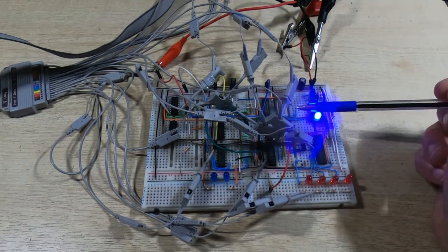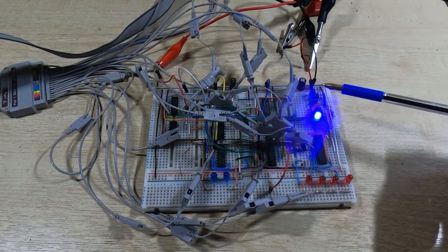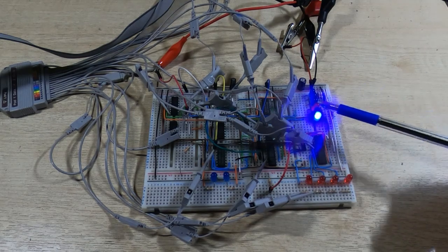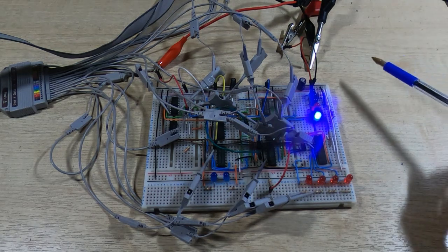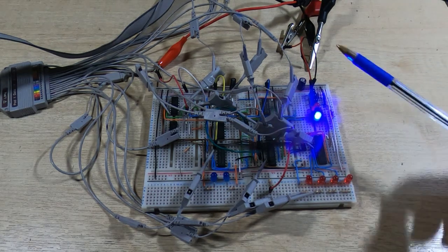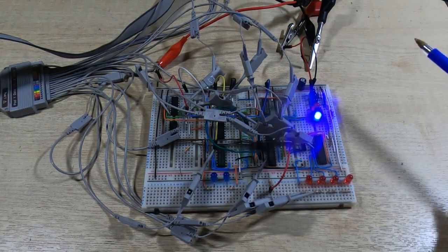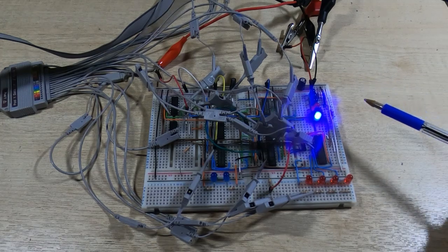It's already got the capability built in to allow the Z80 manual access through the in-out ports to the floppy drive controller device, and it's also got the ability to provide the required clock pulse to the counter when we want to load a value into it. So it has all the requirements to give us full control of the floppy drive interface.